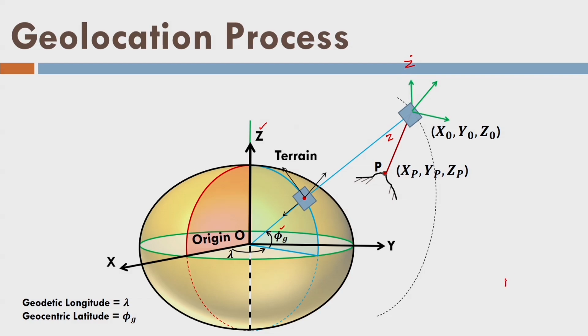So, I can write here the first rotation; we have rotated about the y axis. Now, we will rotate about the z axis. This is the x axis, this was the y axis before, the x axis after rotation, and this is the z axis. This is parallel to capital X here, this axis is the same, and this axis is parallel to capital Y axis here, and now you can see that this angle here is lambda. Let us rotate about the z axis by minus lambda like this. So, now we have the rotation about the z axis by minus lambda.